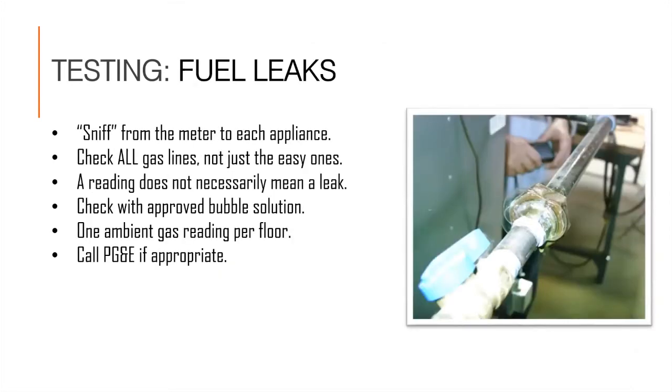For fuel leaks, we're using those electronic gas sniffers, and we're sniffing from the meter to each appliance. Yes, that's right. It's all accessible gas lines, not just the easy ones. A reading or an audible siren that detects doesn't necessarily mean you've got a big leak. So we check with a bubble solution.